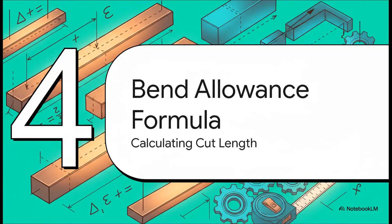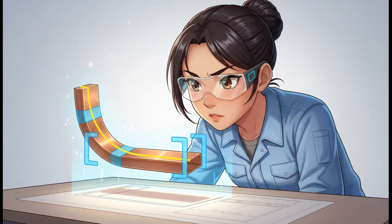Which perfectly sets up Section 4, the bend allowance formula. I know it looks like a lot of alphabet soup, but this standard bend allowance formula is literally your best friend. It calculates the exact length of material consumed as the copper wraps around that neutral axis arc we were just talking about. It's really just simple geometry. Pi over 180 converts your bend angle into radians. Then you just multiply that by your inside radius plus the K-factor times the thickness, boom.